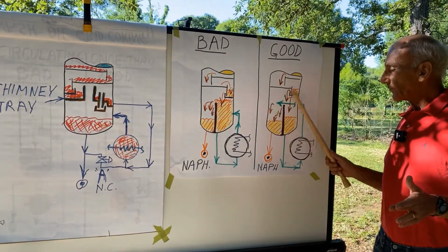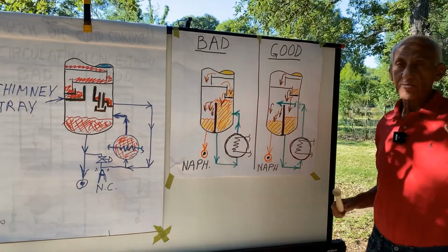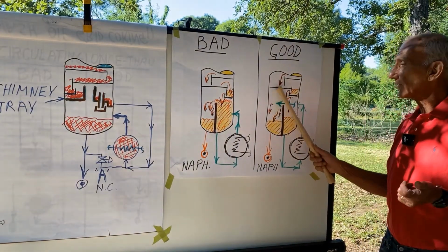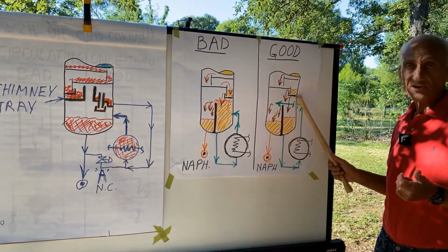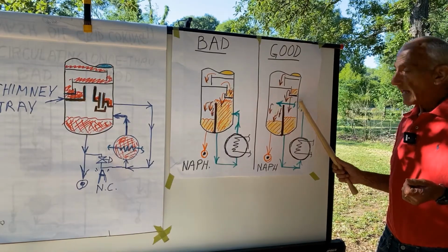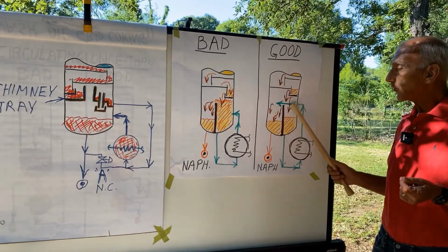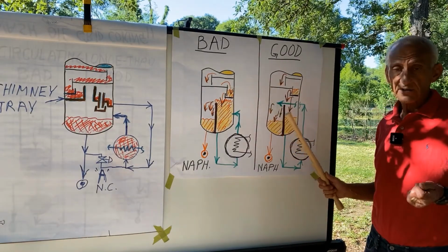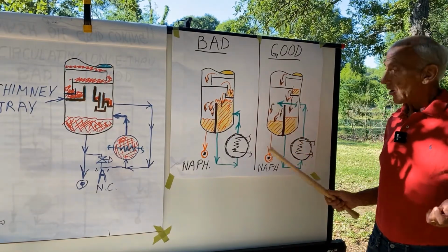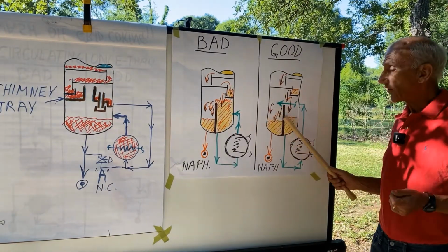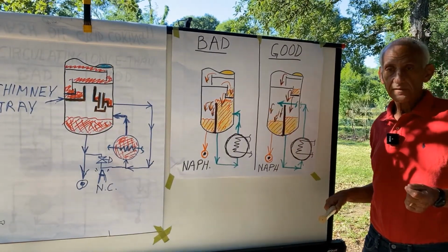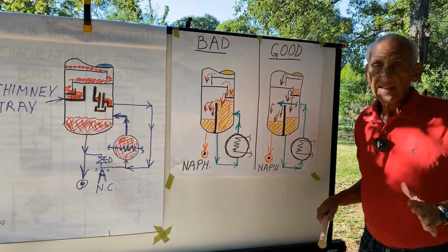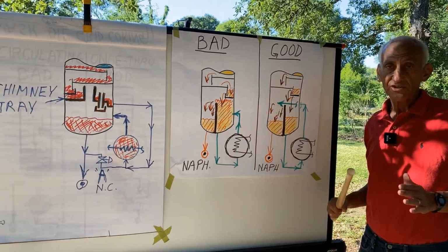Now all the liquid feeding the once-through thermosiphon reboiler comes from the bottom fractionation stage of the tower, as it should. And now the entire liquid portion of the reboiler effluent overflows, as it should, onto the hot side of the overflow baffle, thus greatly improving the efficiency.